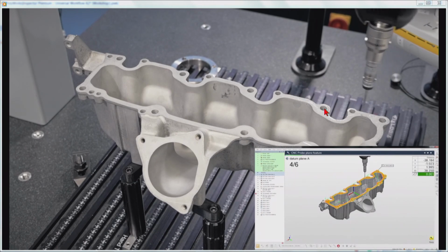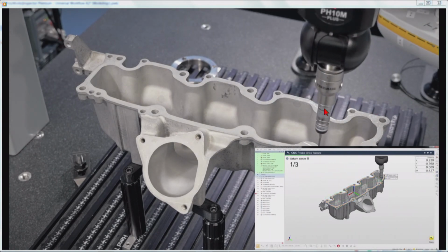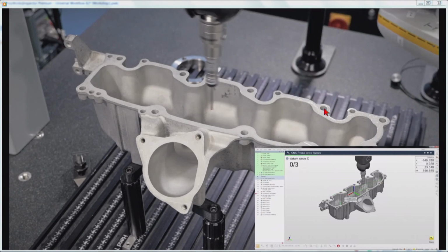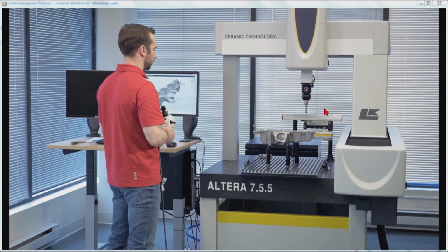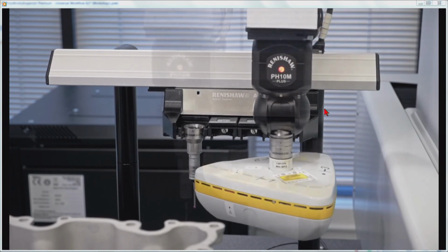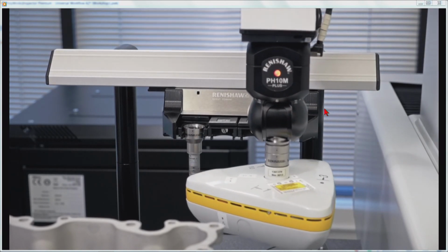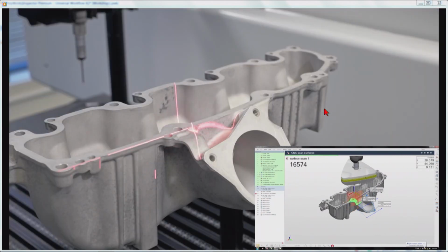Once this is over, it will measure our datum circle B and our datum circle C with 3 points, as we did for the portable arm. So we really have the same inspection going on here. Then, once this is over, the CMM performs the tool change after we've done our ABC alignment, and this is where the laser scanner will start gathering data from the front flange.